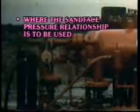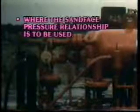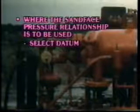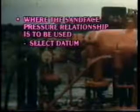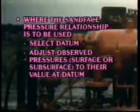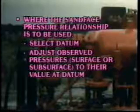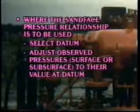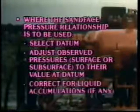If the bottom hole pressure relationship is to be used, a pressure datum should be selected at the midpoint of the producing interval open to flow. Sand face pressures at datum corresponding to recorded static and flowing surface pressures should be calculated using appropriate correlations. If subsurface pressures are recorded, they should be corrected to datum. Also remember to correct for any liquid accumulations in the wellbore. You will now have all the necessary data in proper form for plotting.